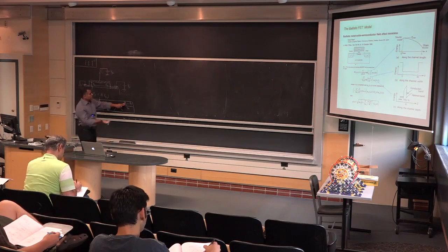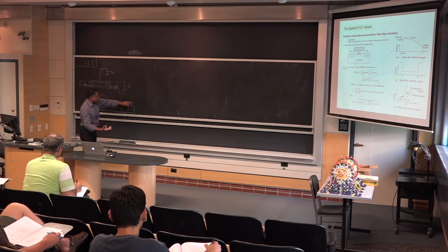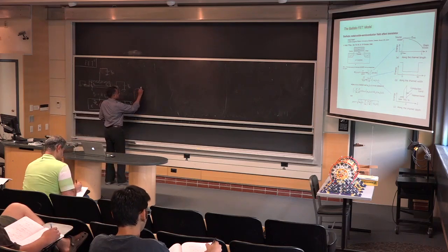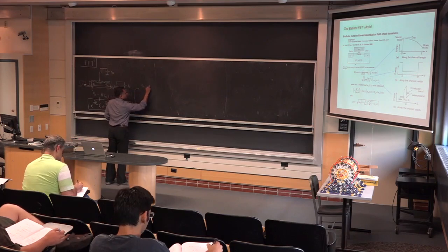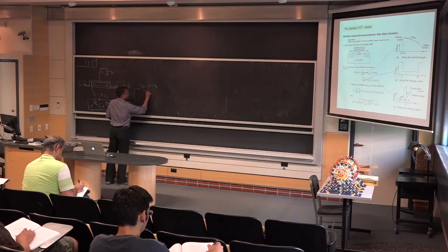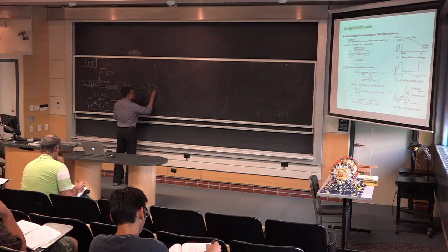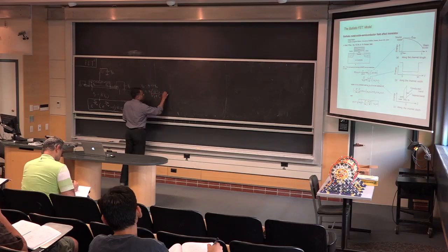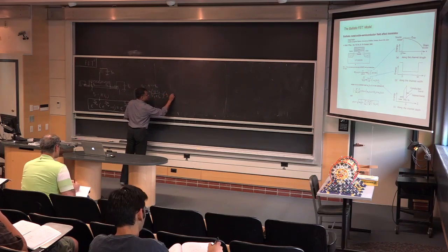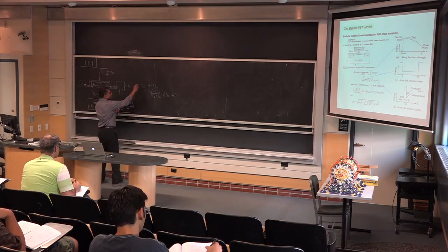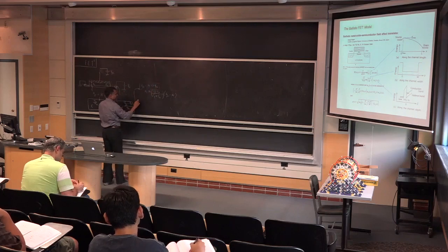When gate voltage was much larger than the thermal voltage plus VT, that is, for VGS minus VT much larger than the thermal voltage, we saw that carrier density went approximately as the quantum capacitance and the barrier capacitance, the two in series, times the gate voltage minus VT. That's what we found. This is a linear relationship with no dependence on temperature. This was the on state, in some sense, of the transistor.